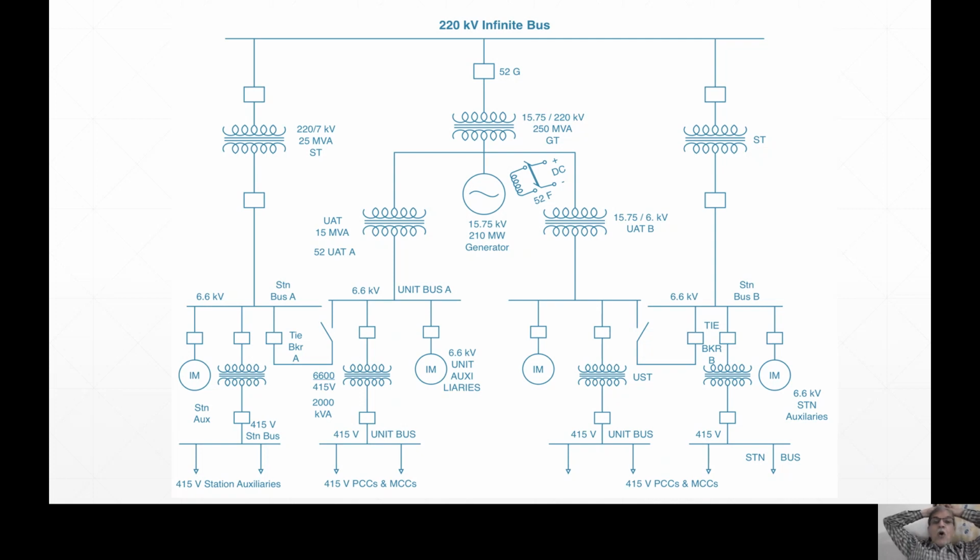Boiler trips. All 6.6 kV auxiliaries, 415 volt motors, everything will come to halt. Complete power plant will be silent. And it's a very big thing. The chief engineer has to report to 7 persons in the state that one of the generators has tripped. And even if he does not say, the load dispatch center knows that the generator has tripped.